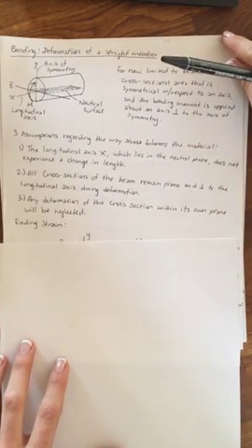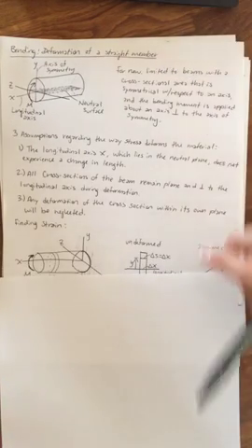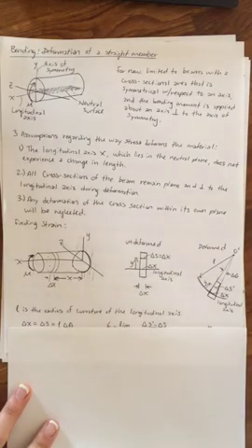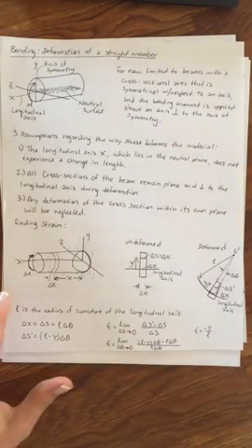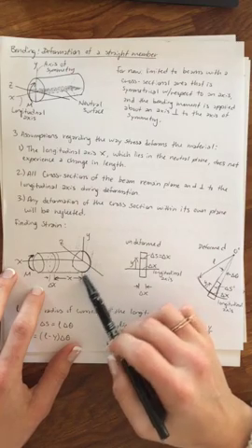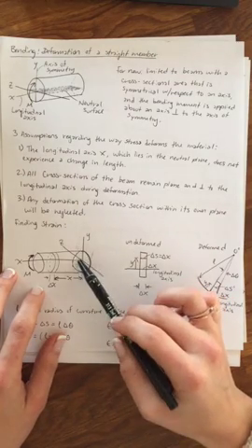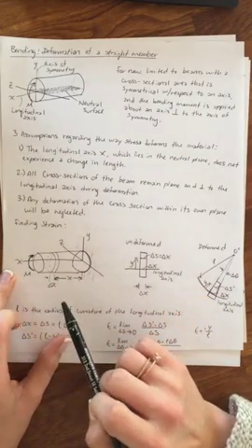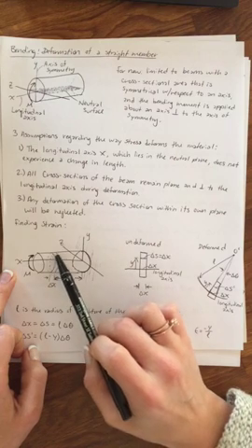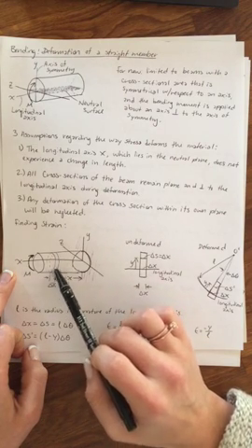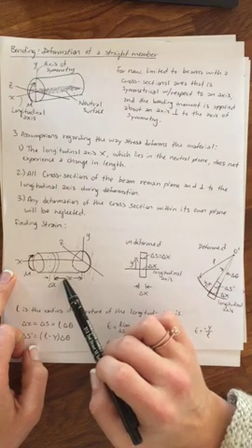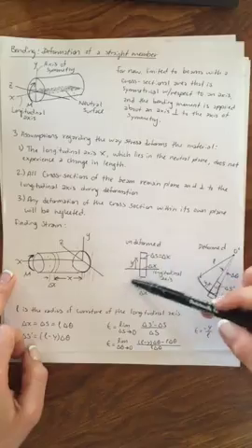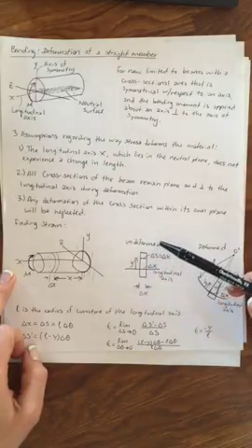All right, now we can talk about how to find strain in this case. So what kind of strain this stress produces of the moment. So in the case of this member fixed to the wall, and we have these axes, the longitudinal axis, and the moment being applied upwards in this direction, we're going to take out a section so we can think about this in a differential way. We have a delta x, and then this distance down the longitudinal axis. We have our little segment here separated out.